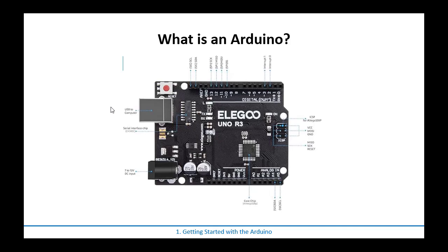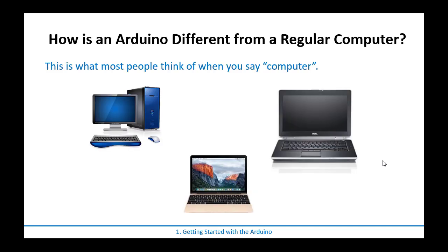If you chose not to have a cable connected, like you wanted to put this on a robot and not have it tethered to anything, you can power the Arduino board from this little jack right here, and this takes in 7 to 12 volts, and this is for like a bunch of AA batteries connected in series. So that's the Arduino that we are going to use.